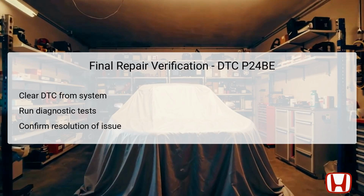After completing all necessary repairs and replacements, the final step in the troubleshooting process for DTC P24BE is to verify that the issue has been resolved. Begin by clearing the DTC from the vehicle's onboard diagnostic system to reset the parameters. Following this, rerun the diagnostic tests, including the HDS tests previously used, to ensure that the previously indicated problems have been resolved and that no further trouble codes appear.